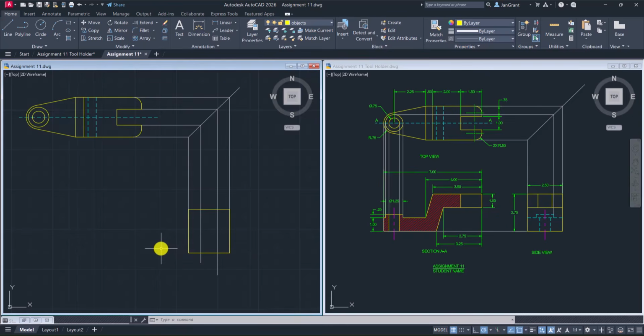Okay, now we do know, based on this section, that this is 1. So this little leg that's from the top view is 1 down. So let's start the offset command. Type in 1 and enter. Click on this top line and pull your mouse down and click and enter. So now we know where these two lines are, right here.